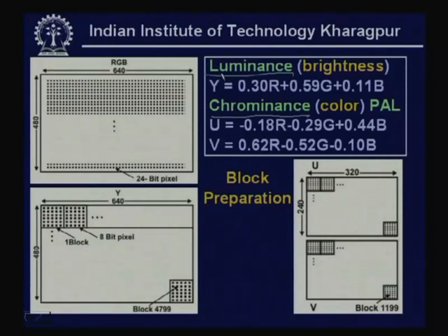So, chrominance can be sent with lesser resolution. Secondly, converting to luminance and chrominance components allows more compression than if it is present in RGB. That is why the digital video signal is converted into YUV components.